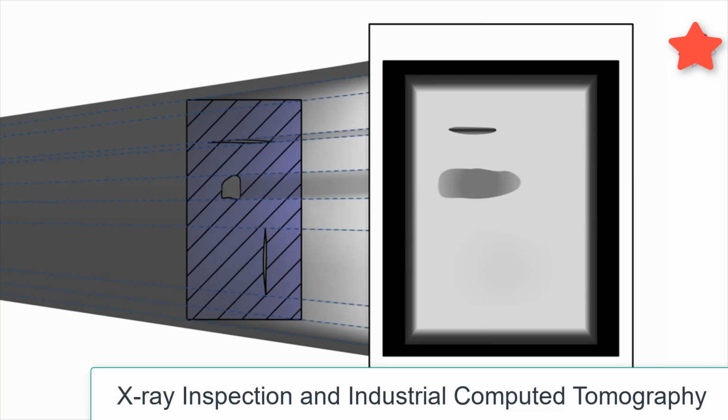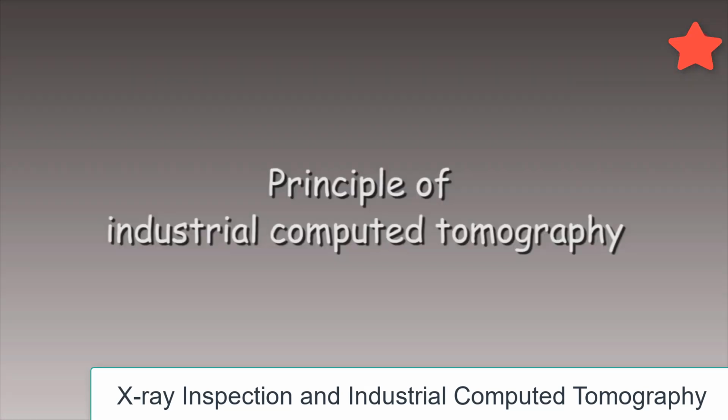The position of the defect in depth, that is, in beam propagation direction, cannot be determined with a single X-ray image alone. It hardly makes a difference in the image whether a defect in the sample is positioned further to the left or to the right. In order to determine the depth of location of a defect, at least one additional X-ray image has to be taken from a different direction. Computed tomography pursues exactly this approach, not only by taking one, but in fact many additional images. A fantastic method. How does it work?